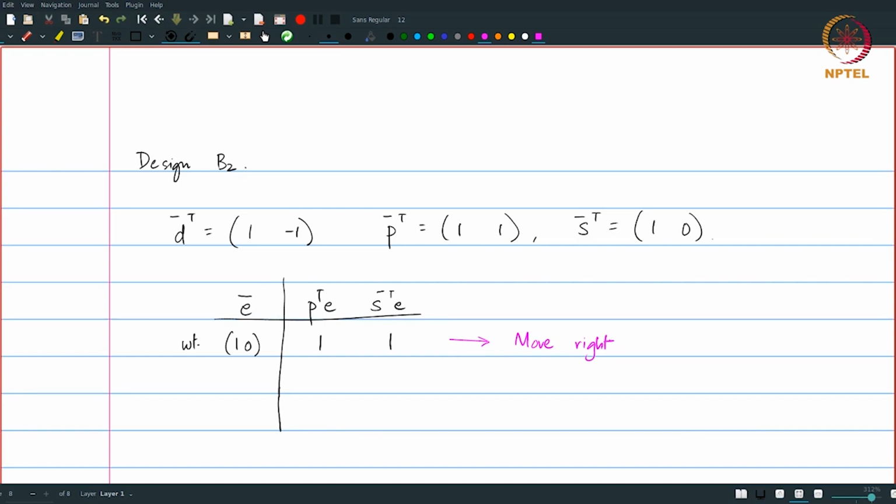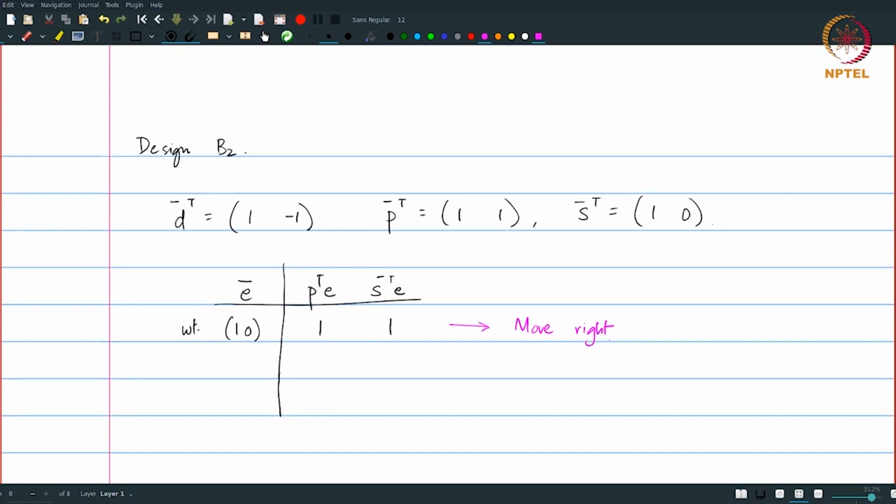Now, what does that mean? It basically means that a weight is going to get moved from P0 to P1, and then from P1 to P2, and then from P2 to where should it go? We don't really have a requirement for more than 3 processors, but this is where, as I said, some amount of interpretation of the results also matters, because the equations just tell you that after moving to P2, the weight will then move on to P3. But we know that we do not require more than 3 processing elements because there are only 3 distinct weights to be computed. And if we look more carefully at the dependence graph, we can find that P3 can then be mapped back onto P0 itself. We will make use of that when we finally construct the architecture.